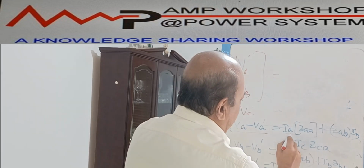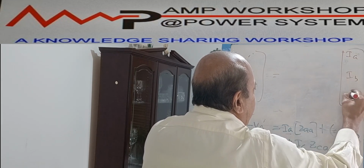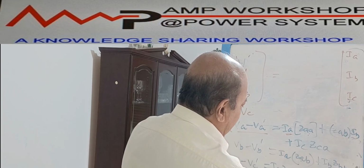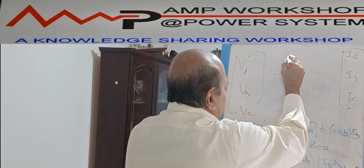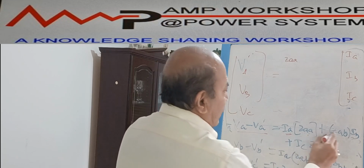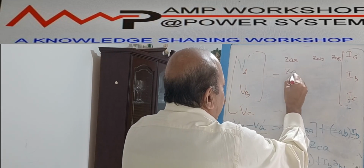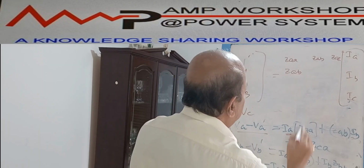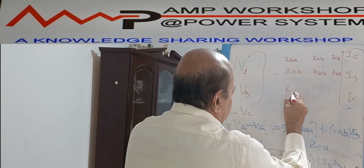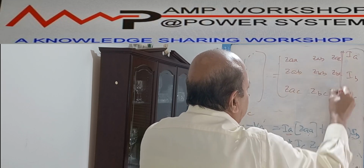That is equal to, you see here, current IA, IB, IC everywhere. So there will be one matrix of IA, IB and IC, right? And then here the IA current has ZAA, here ZAB, and here the IA current has ZCA. So we can write it this way: ZAA, then here ZAB and ZAC, right? Second is ZAB, then ZBB and ZBC, right? Third one is ZAC, ZBC and ZCC. This is one matrix you are getting, right?